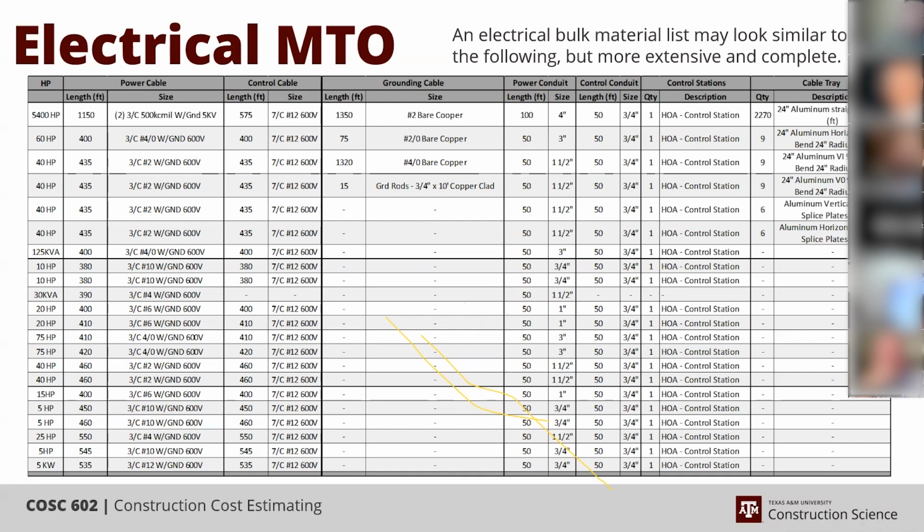They can be 24, 36 is pretty common, they can be 42, 48 inches wide, and they can be as narrow as 6. So you can run a handful of cables away from the main pipe rack cable trays, stepping it down, but once it leaves the tray, it's going to enter conduit until it reaches its final destination.